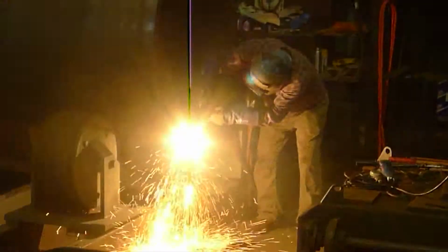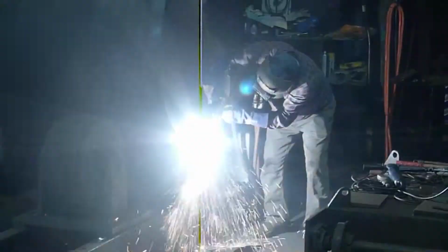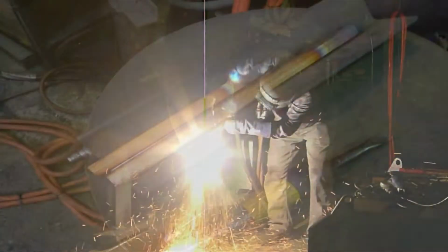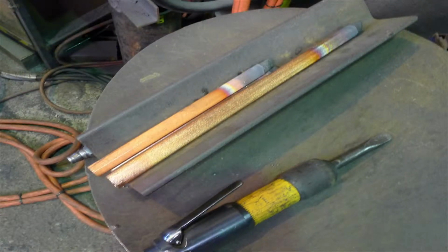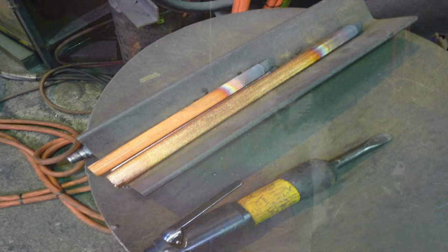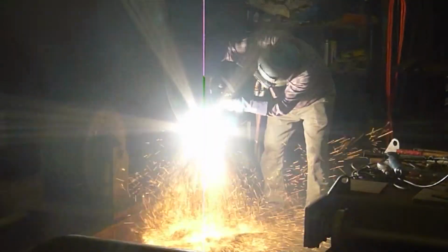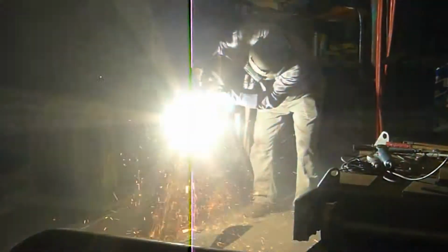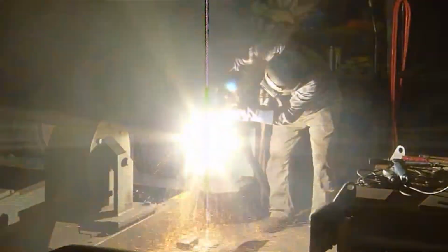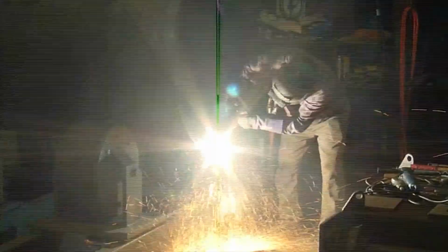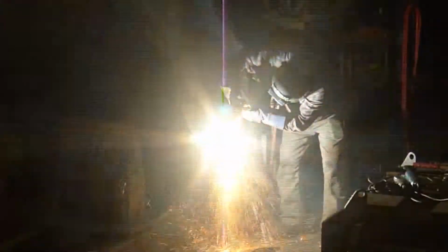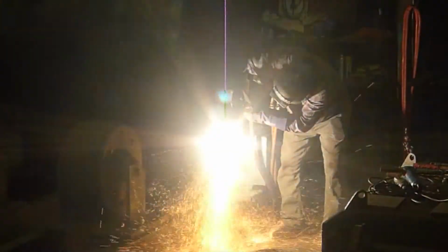This cutting process is known as air carbon arc gouging. An electric arc is generated between the tip of a hollow carbon electrode and the workpiece. The metal becomes molten and a high velocity air jet streams down the electrode to blow it away. The process uses the same equipment as gas metal arc welding, with some modifications, has a high metal removal rate, and the gouge profile can be closely controlled.